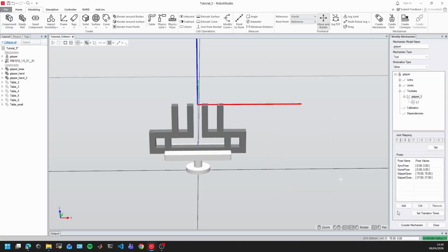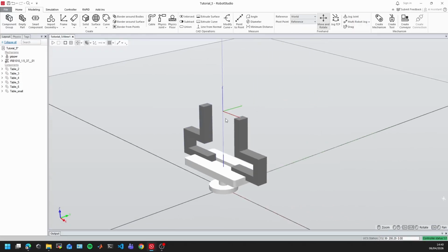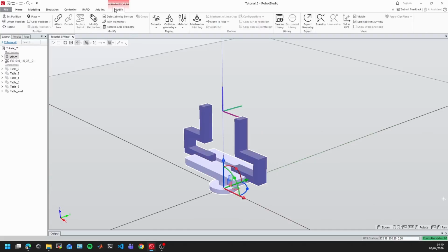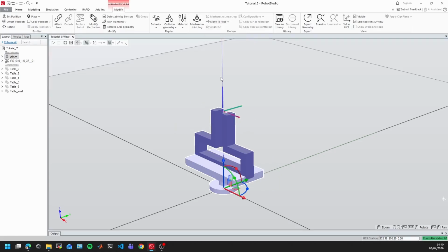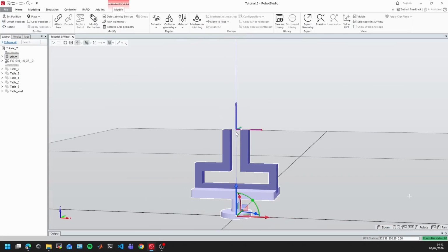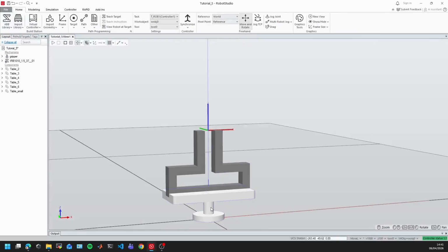So OK, and then in here I don't have to compile anything else because I just did it. But there you go. Now you can see the TCP. If I put modify and I move to pose to gripper open, gripper close, and home position, you see the TCP always stays in the center. That's why we have to put this with reference to the base, because the base is the one that doesn't move. The ones that move, you can have a reference with the movement.